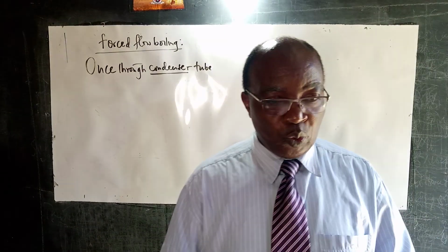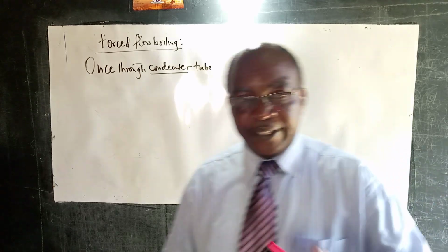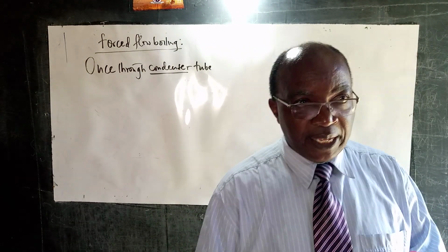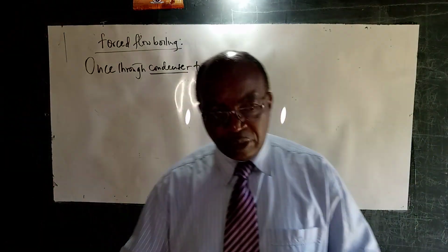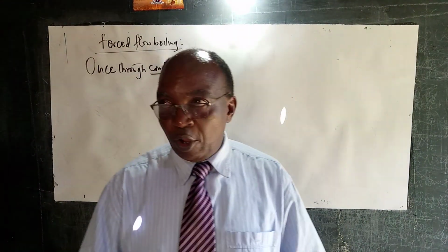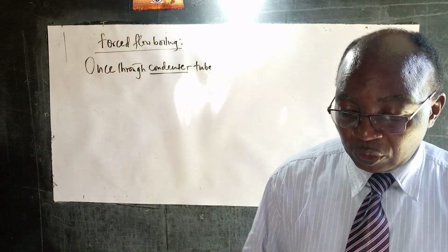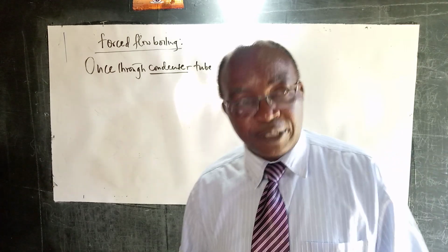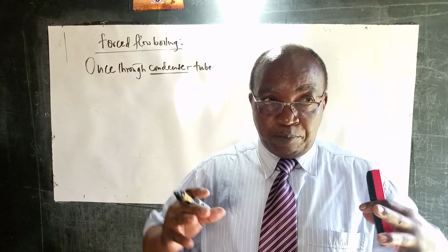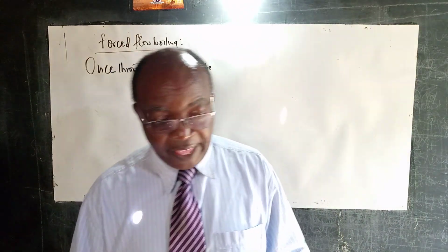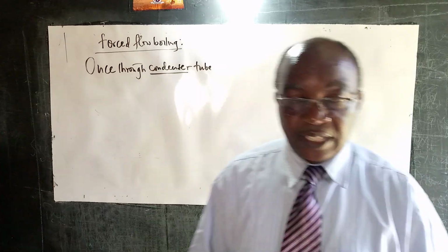And why is that so? Because remember, in the forced boiling system, we'll have a two-phase system. We'll have both liquid and vapor. And if we were to use a horizontal tube, then there will be no symmetrical flow in that particular system. So the vertical position is a much easier and simpler position to account for than if you're dealing with a horizontal tube and a two-phase system.